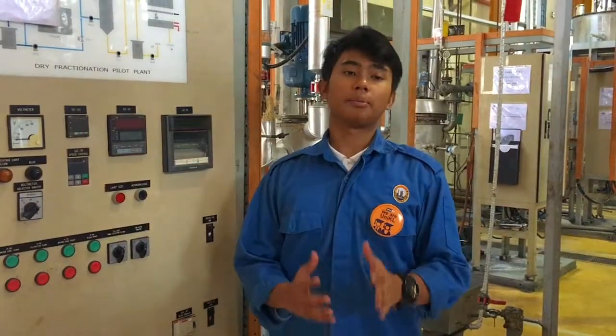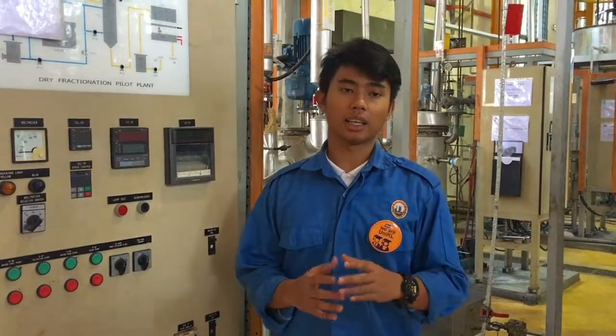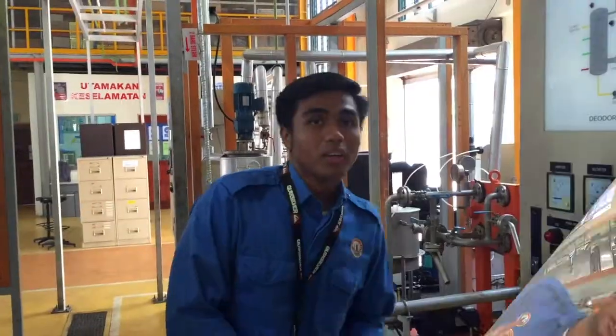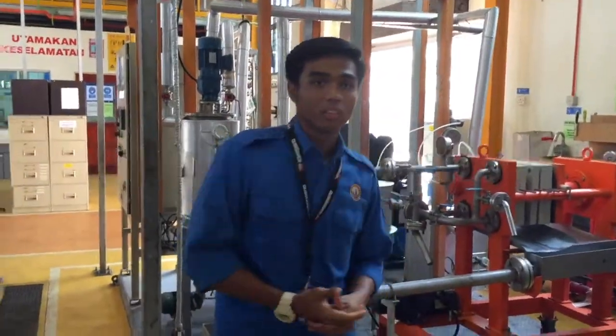The crystallization system is a batch type and is equipped with special crystallizers operating alternately. The crystallization process is carried out to remove higher melting glycerides, which cause liquid oils to become cloudy and more viscous at low temperature.